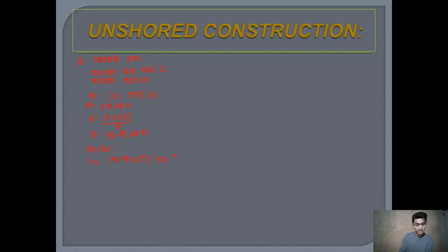Take note, we are considering steel and then concrete section again, the whole composite beam, divided by our transform moment of inertia, which is equal to 723.903 times 10 raised to 6.